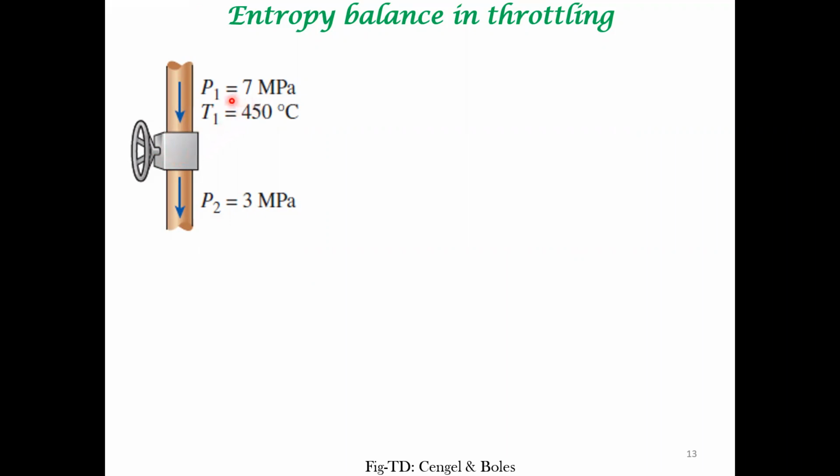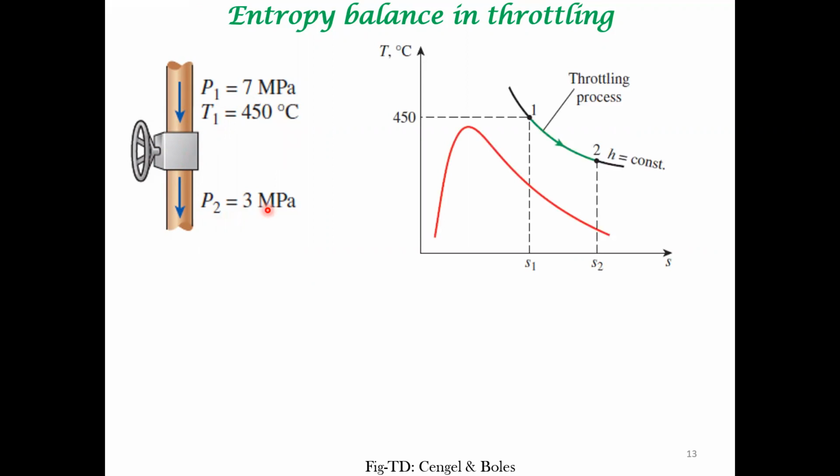So you have some pressure at the inlet. Because of the valve, the pressure decreases. How do we characterize this system? We say we do a balance, and the enthalpy is said to be a constant, right? So we can analyze these systems. We've already analyzed such systems.